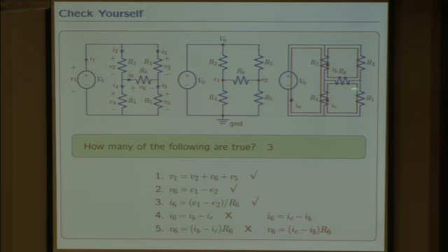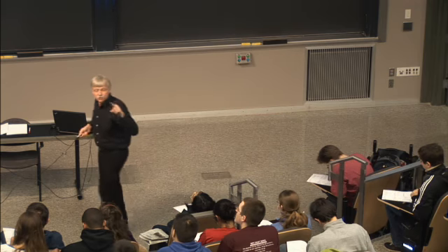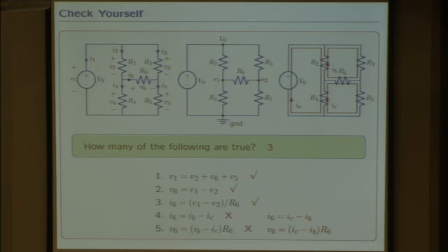There are two loop currents. We have to worry about which one goes through in the correct direction. I6 goes from left to right. So when we do the loop currents, we need to take positive as the direction from left to right. Well, that's the direction of IC. And it's opposite the direction of IB. So if I want to use loop currents to specify I6, it would be IC minus IB. Everybody clear on that?